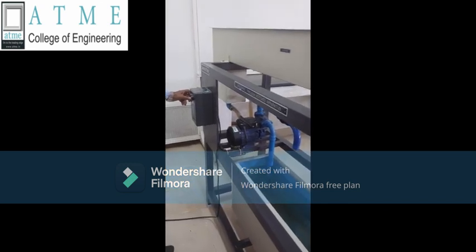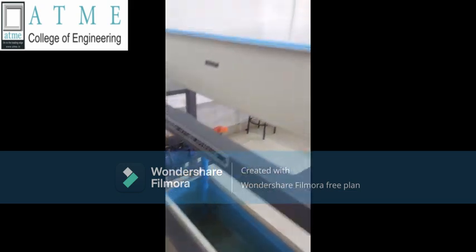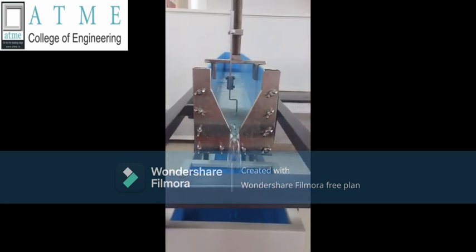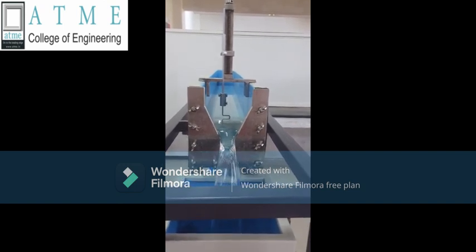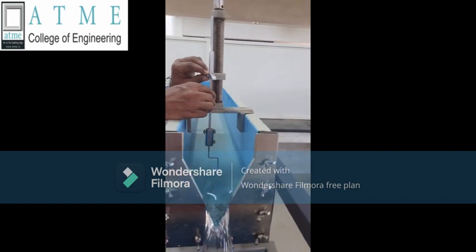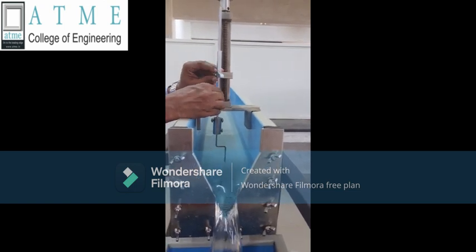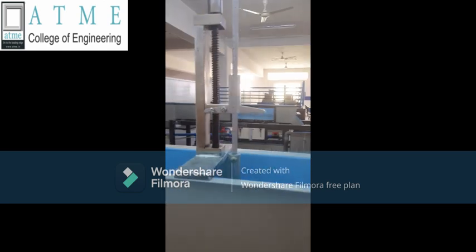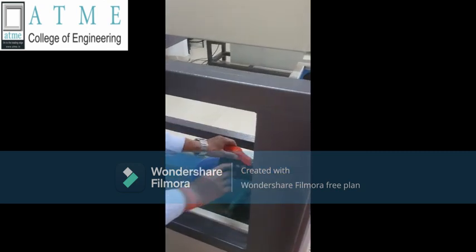Switch on the motor and close the flow regulator valve completely so that the maximum discharge is allowed to flow in the channel. So once the flow becomes steady, again adjust the point gauge. The tip has to touch the top surface of the water. After adjusting the point gauge, note down the reading H1 for maximum discharge.